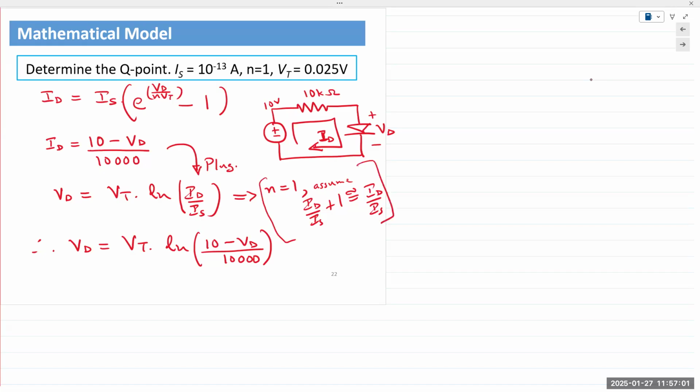Okay. So what I've done here is I'm trying to solve this mathematically. I took the diode equation, and I can rearrange it to obtain an equation for the diode voltage, right? We simply take IS to the other side and take the natural log on both sides, and we obtain an expression for diode voltage. I want to keep the number of terms as low as possible, meaning I have one thermal voltage in there, and then I have VD.